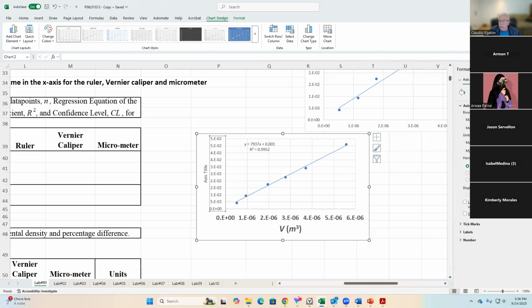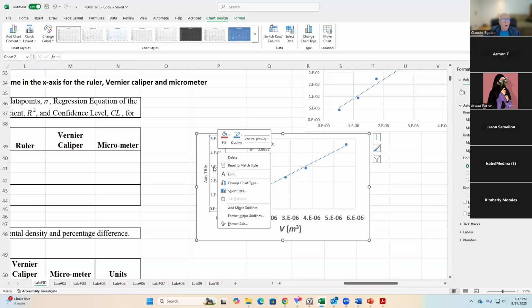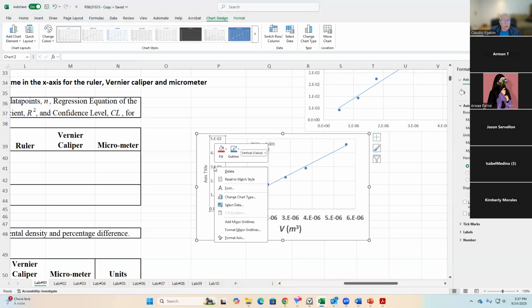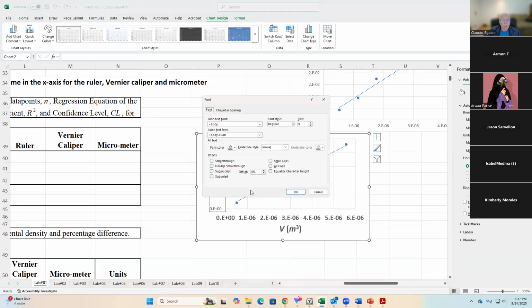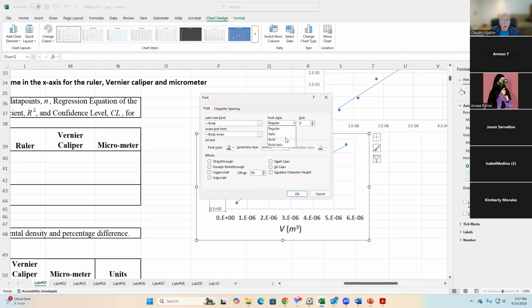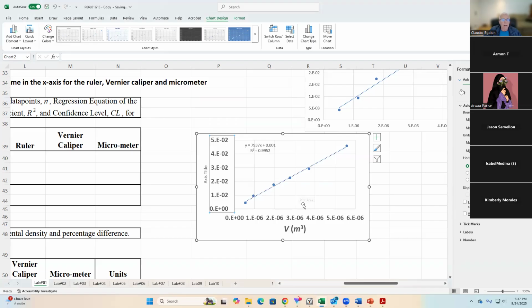If you put 0.00, let's see here, minor, yeah, put 0.01. Let's see. Yeah, good. And now it populates with fewer numbers, right? Because I increased the distance between them. It's okay to do that. And let's increase the size as well. And to make it nicely visible, let's boldface it. Font, regular, boldface. The size was 14 that we used, right? And now, yeah, now we have it.